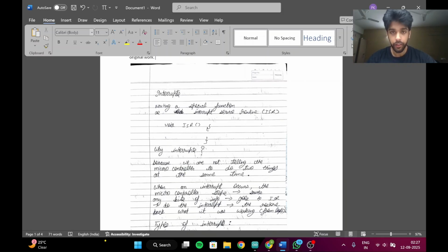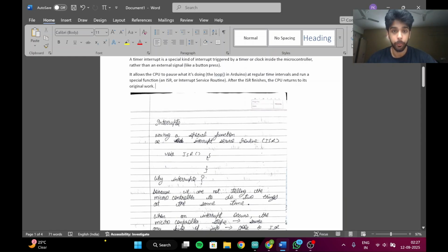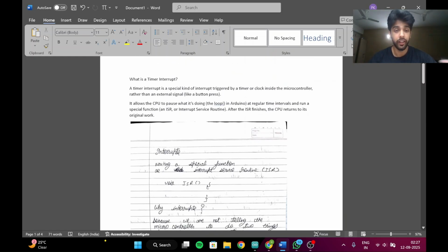It is a type of interrupt generated inside the microcontroller, for example, the timer interrupt. If we say to fire a timer interrupt, which we will be doing in this task, because we want an LED to follow an interrupt after every 1 second of the timer, that's how it is periodically fired.